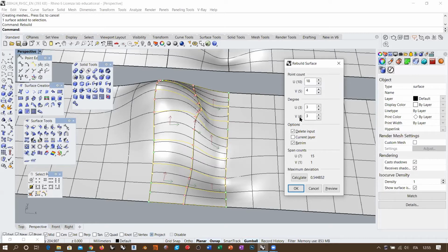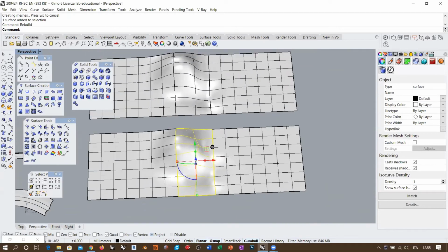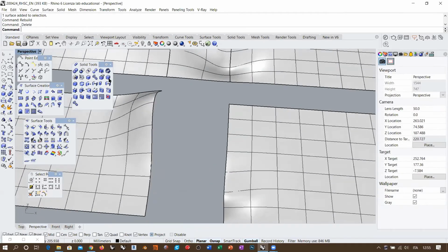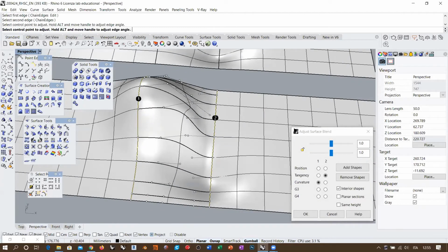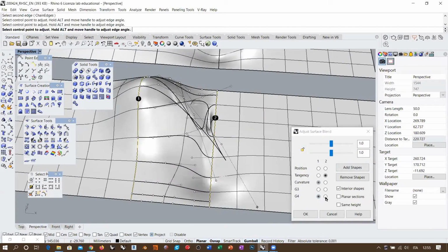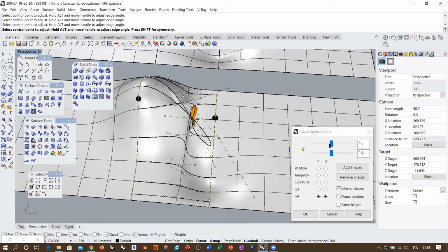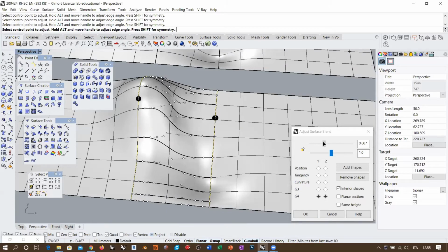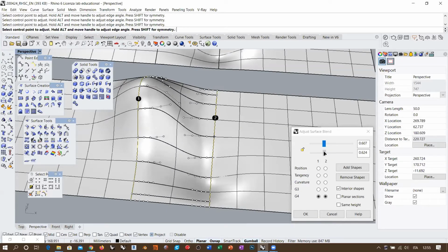And we are seeing that the blend command sets the degree according to the number of control points. That's the only thing that it can do. So when you define the amount of control points, automatically you have a degree which is equal to the amount of control points minus 1. So you can imagine what happens if I take a blank surface between this and this and set this to G4, G4, and eventually avoid some self-intersection along the way, okay, like this.